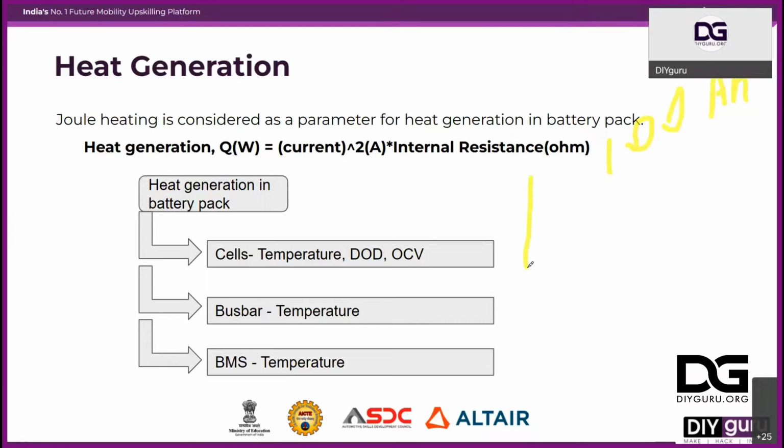Consider this is your cell. If you think this is 100% and this is 0%, the energy the manufacturer is claiming is 100 Ah of cell. But your cell won't move from 100 to 0 like that. It has some depth of discharge, so the usable energy starts from about 85%.